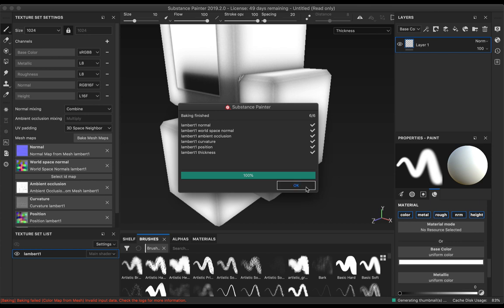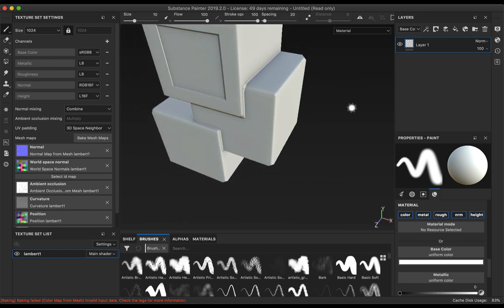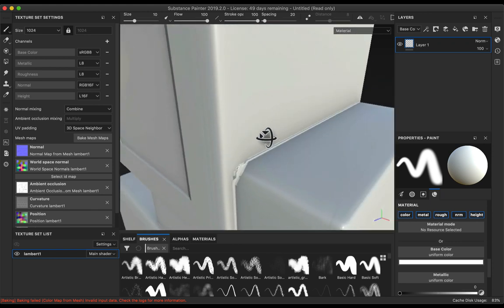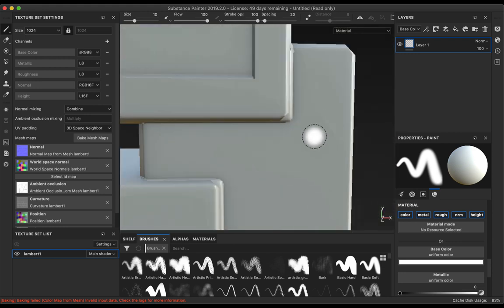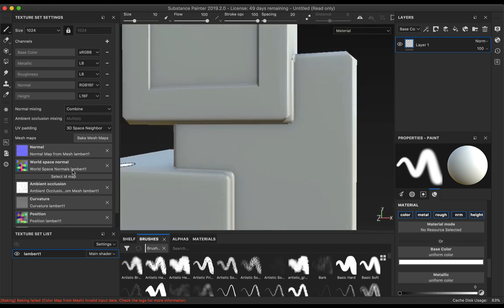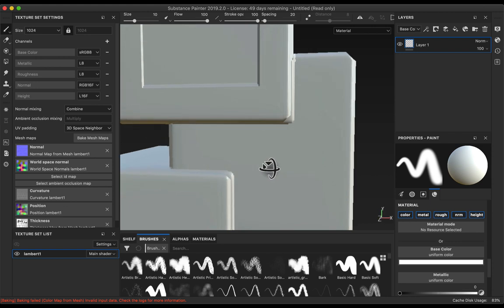So doing that fixed the edges. I opened that threshold up a little bit more and it was able to see the high-end game res. But we have this problem now. This is a problem that the bake is never going to fix. This is because my game res model has a sharp corner to it from being beveled, but my high res is round here. So this, there's no way around.